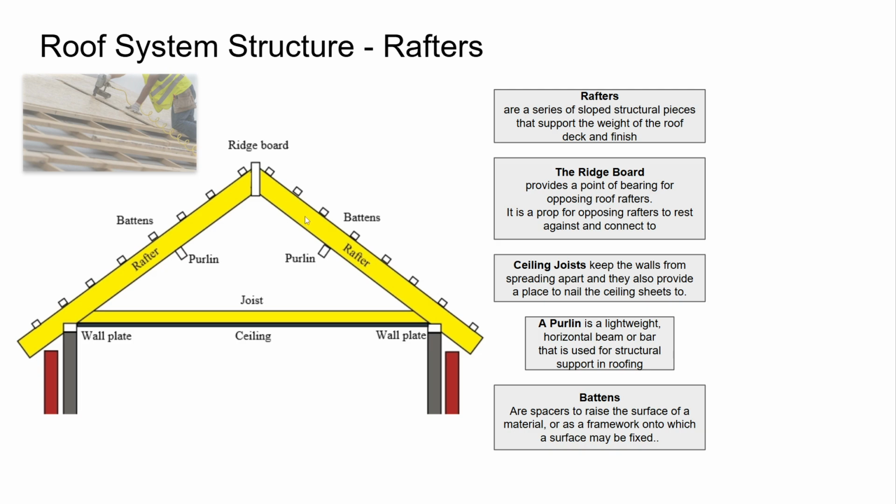Okay, and then there's battens. Battens run across. Here they are up here. These are battens, and they're showing what they're used for. It's so that you can put your roofing material into something and nail it into place. You can imagine just nailing it into the rafters that are widely spaced might not give enough purchase, and your roof decking, these boards, might try to sag.